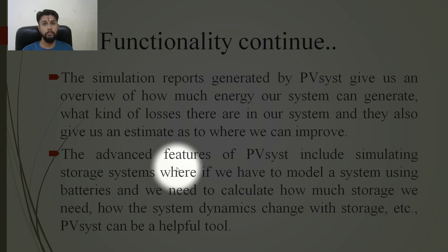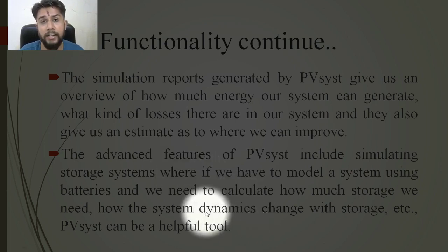For this, we require the consumption limit of that consumer, as well as how much storage capacity we require at this place, considering the number of days of autonomy, the power failure, etc. This dynamic design we can easily carry out with the help of PVsyst